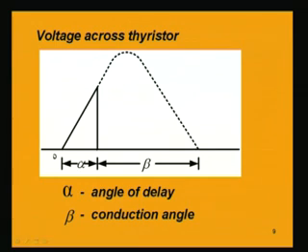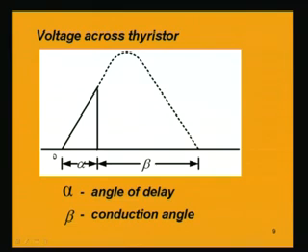It is 0. Although the voltage after turning on is a very small voltage, not 0 to be precise, and normally it is greater than the diode on voltage. A normal diode has a voltage after conducting of around 0.7 volt for silicon, but for a thyristor that conduction voltage after turning on is greater than that of an ordinary diode. But for all practical purposes we will consider this voltage to be 0 because we are dealing with power circuits, power control. So, the voltages which we will be handling are quite large. In comparison with those voltages, this small voltage of the thyristor after conduction can very well be assumed to be 0. So, as soon as the conduction takes place, the firing occurs in the thyristor, the voltage becomes 0.